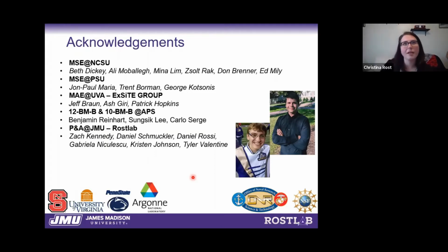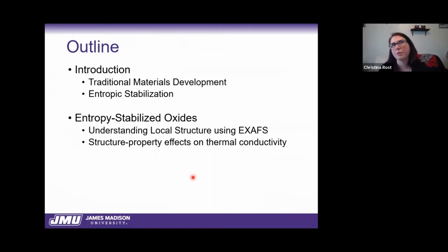Okay, so my talk today is going to be in 3 sections. My first section, I'll just give an introduction based on the traditional concepts of materials development, and I'll introduce the idea of entropy-stabilized oxides and entropic stabilization. And then from there, I'll dive into how we used EXAFS to understand the local structure of these novel complex oxides, and then a little bit about the structure property effects on thermal conductivity, which we again used EXAFS to kind of confirm a hypothesis that we figured out through modeling.